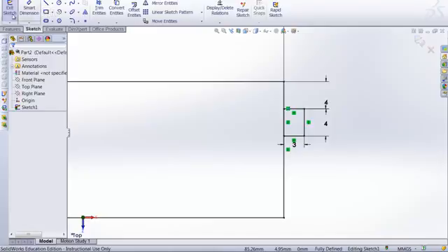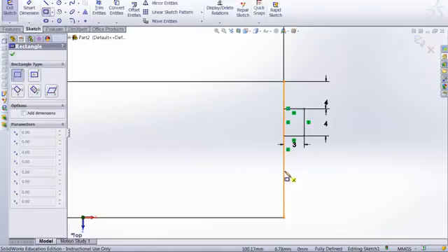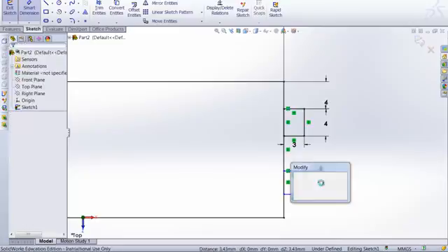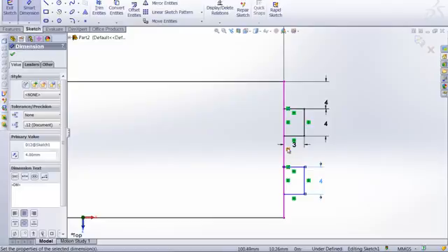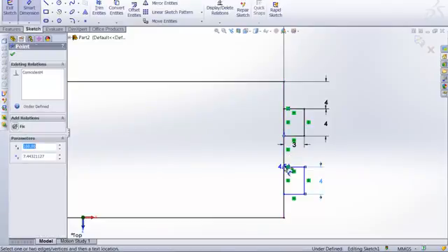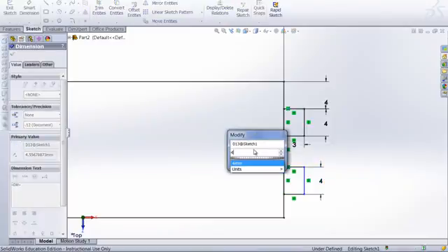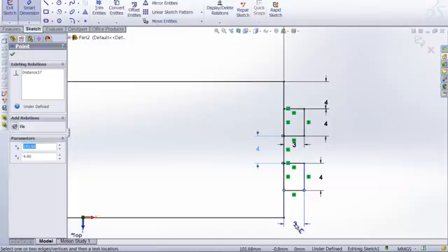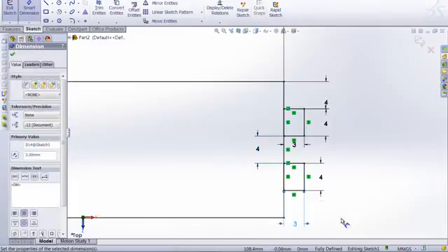And again, let's still make sure we've got this sketch tool. I'm doing another one, so I'm just drawing anywhere. Okay, so now I need a smart dimension again. I still need to tell SolidWorks that is 4, and most important, smart dimension also needs to define the distance between those two teeth, which is 4. And hit enter, click, and it's done. But I have not defined something else because this is underdefined. That's because I haven't defined the width of my rectangle. Okay, now my shape is fully defined.